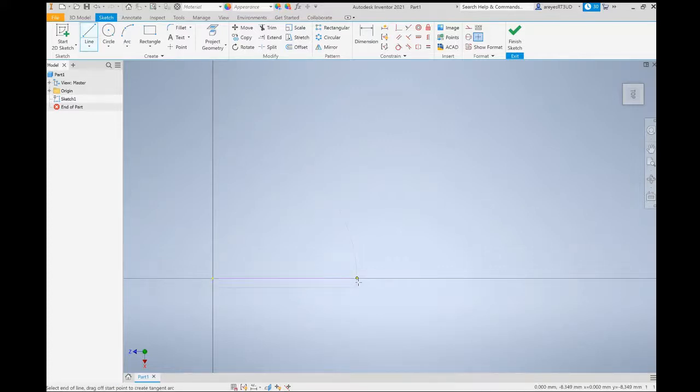You can actually do freehand or maybe have, let's say, an image. You can upload an image here and trace over it and then adjust the dimensions accordingly. So for now I'll just show you the basic. You have, let's say, 10 mm for the measurements, then another 10 mm. So with this you lock in the dimension. So basically this is fixed.